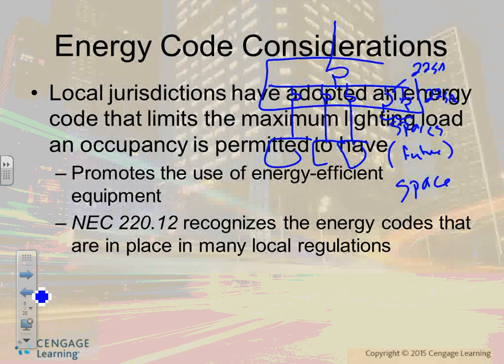You have to put the amps though, because the slot for a 15 amp circuit breaker is different. This is a 150 amp circuit breaker, guys. And this guy is a 15 amp circuit breaker. Look at the slot. Do you think they fit in the same slot? Definitely not. So when you say space, you also have to emphasize what amp for the space. So space or spare? On your schedule, guys, I'm going to ask you to put a couple of spare circuit breakers for future use. Any comment about spare, space, future, and so forth?